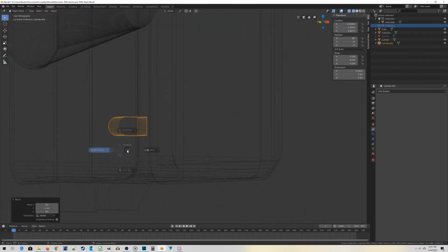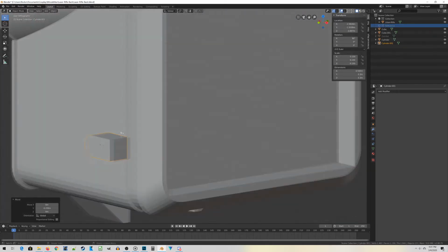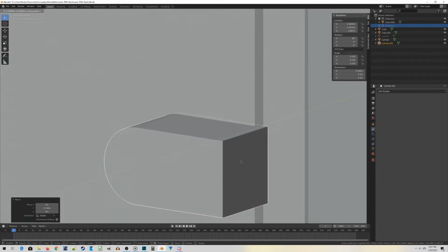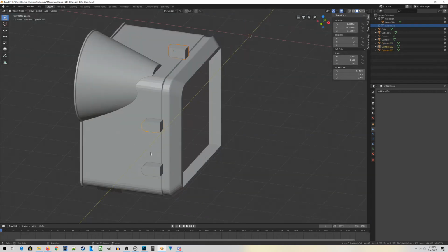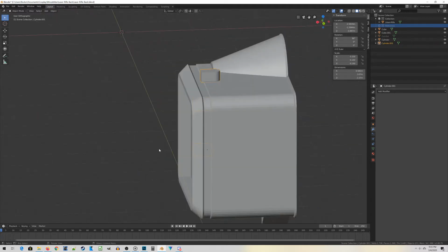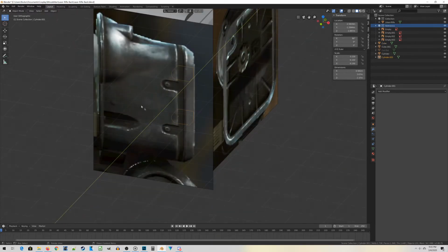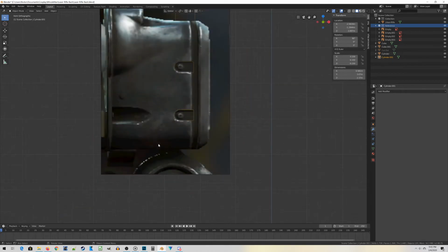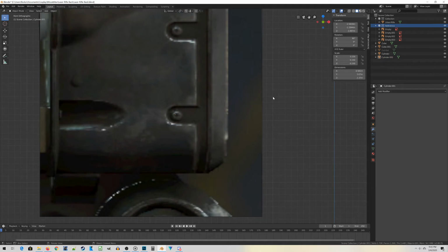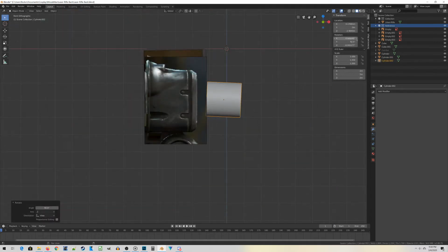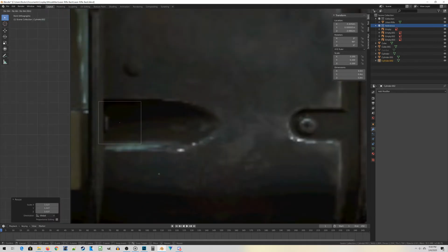All that's going to be is I'm going to create a cylinder and flatten off one side. All three in the right spot. Let's shift left click each of them and do Control J to join them into one object. So now I need to create a shape that more or less can work to cut that piece out. Once again, that's going to be a cylinder, but we're going to do a few other operations. Take a cylinder, rotate it, and scale it down to the right size and or shape.